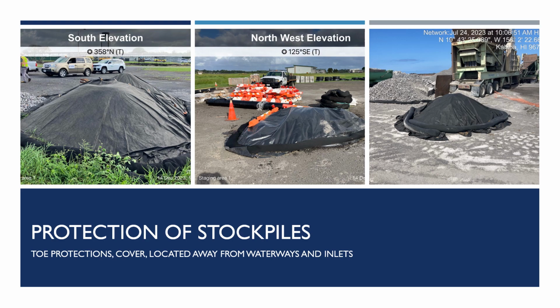Soil stockpiles must be covered with impermeable measures or stabilized and have toe protections implemented around the entire toe of the stockpile. Stockpiles must be stored at a minimum of 50 feet, or as far as practical, from waterways and inlets. Contaminated soil stockpiles must be stored on an impermeable liner or device, surrounded by an impermeable berm, and covered with impermeable measures.